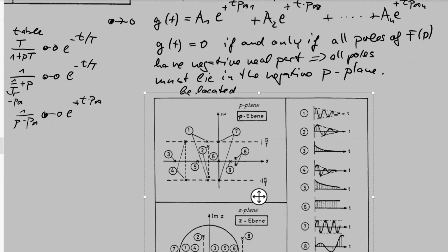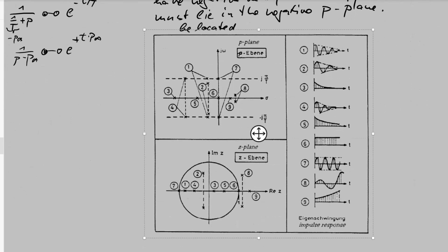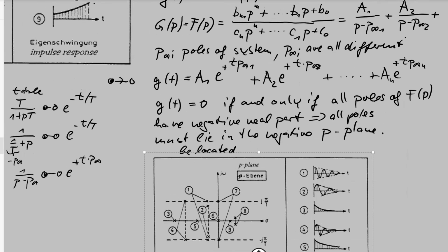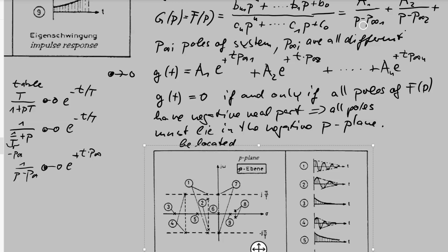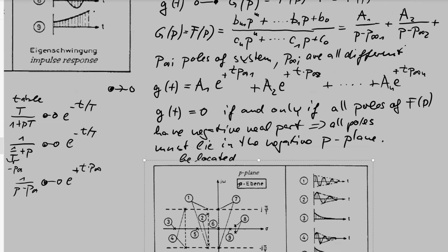Okay, this is a first stability check using the coefficients of the transfer function, with a big disadvantage, because you need the poles. If you cannot calculate the poles, and there are some cases where you can't do this, then this pole criterion is not usable. Of course, if the C's are given numbers, you can calculate any pole with root finders, with numerical methods.